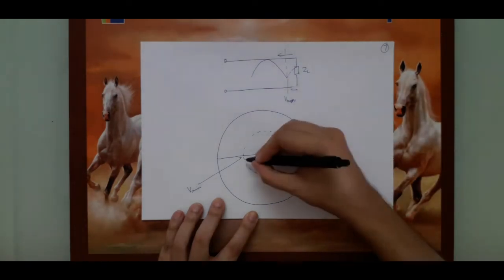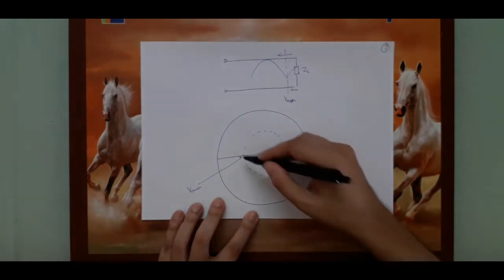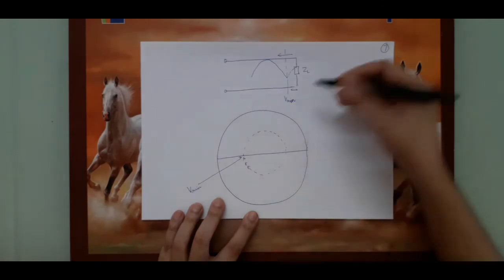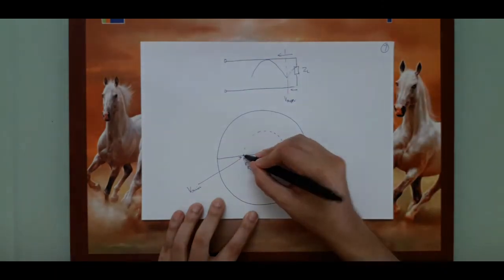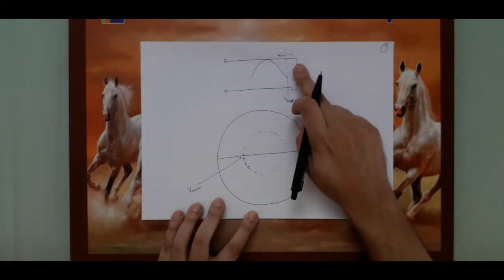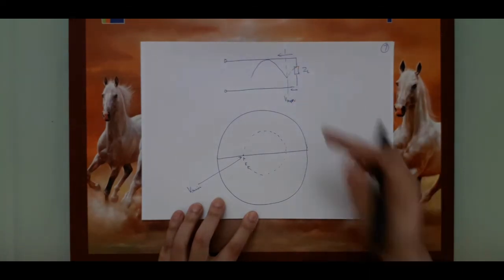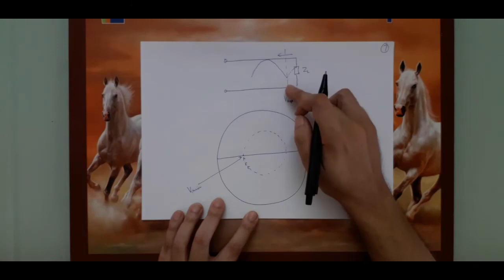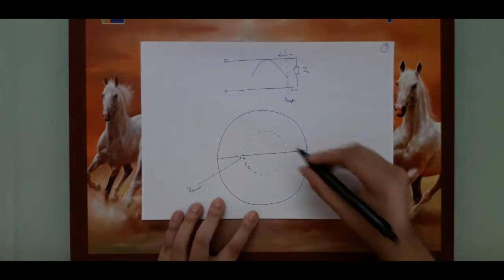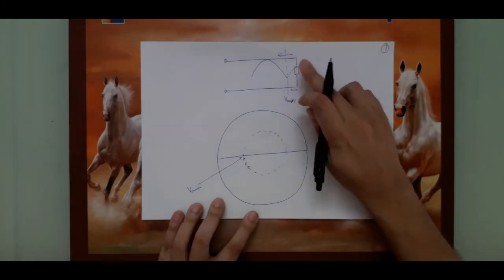That means I must have started from somewhere over here, the below part of the circle, because I am moving clockwise away from the load and suddenly I encounter a minima. We know that the voltage at the load is neither maxima nor minima. That means the first extreme which I am encountering is a minima. We know voltage maxima is here. So definitely this load cannot be here.